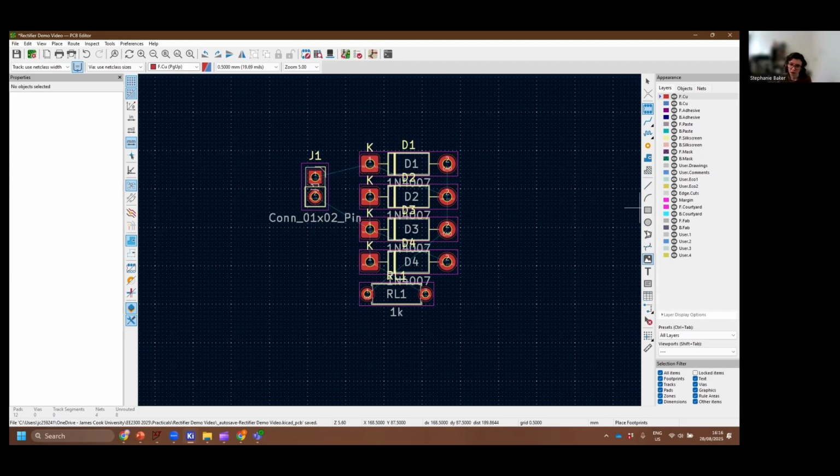A step further to the right again, and you'll see there's all of these layers that have been given to us as a default. So it's defaulted to a 2-layer copper board, so one layer of copper, then some insulation, then another layer of copper on the bottom. And that's what these first two are. So that's F.Cu, our front or top copper layer, and B.Cu, our back or bottom copper layer. So those two are important.